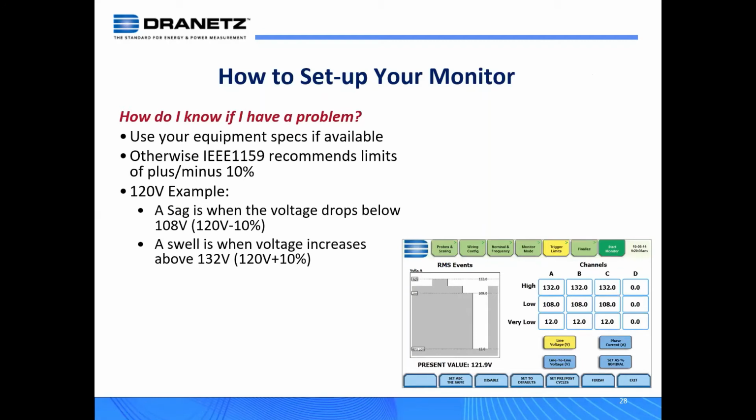However, what I said before doesn't apply to you and your application specifically. So how do you set up your power monitoring instrumentation? The first thing, as a point of reference for your limits, a high limit and a low limit, is that you should really look at your equipment specs.